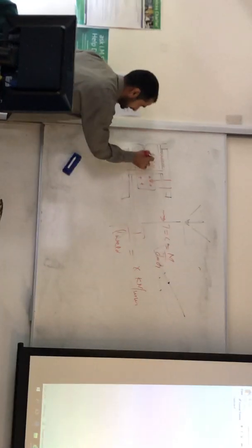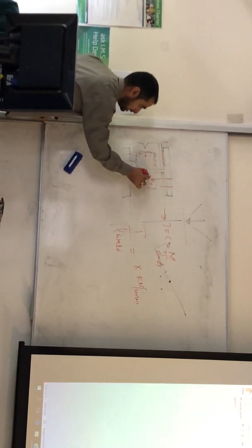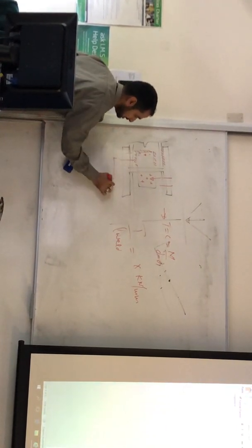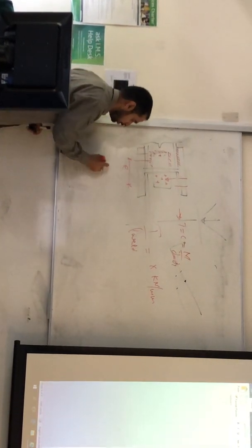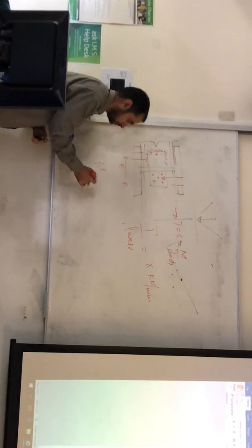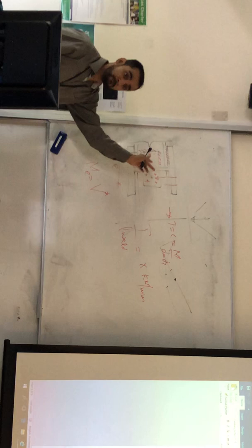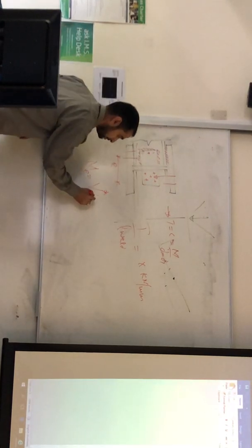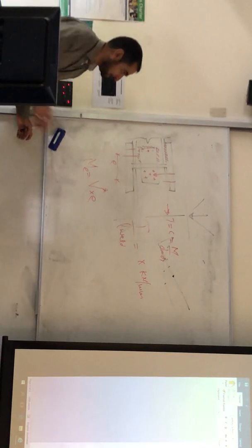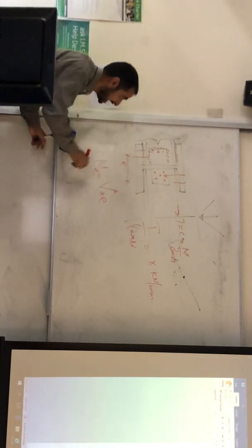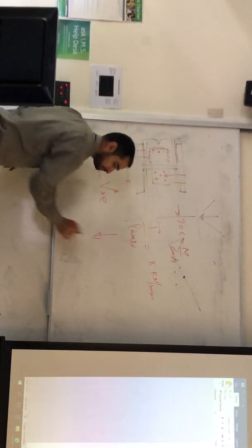Now, there is a centroid of the weld group and the bolt group, and the distance between the two is the eccentricity. Now that eccentricity creates a moment, M_e, or eccentric moment, and that's equal to V star, which is the design shear force at that point in the beam, times e. That's it. So now you got the normal shear, which is V star divided by the number of bolts, that's your vertical component.